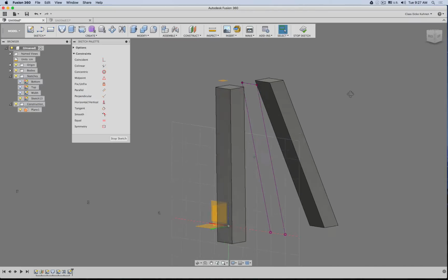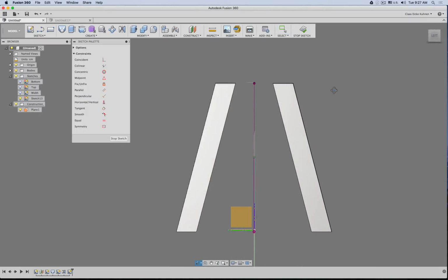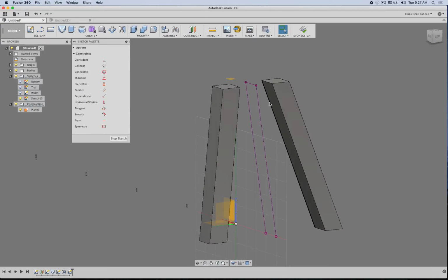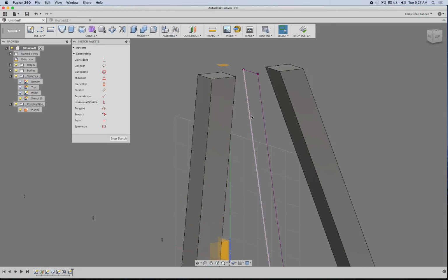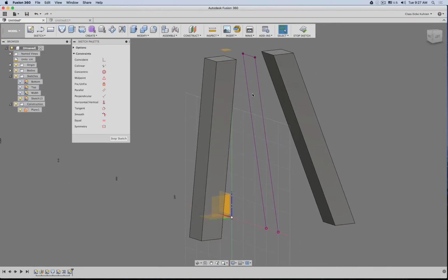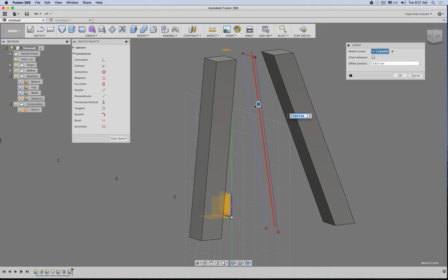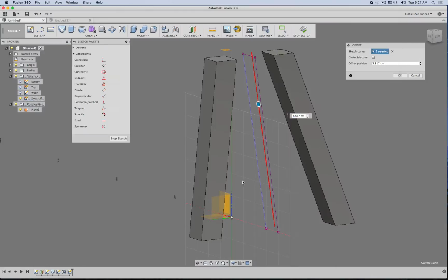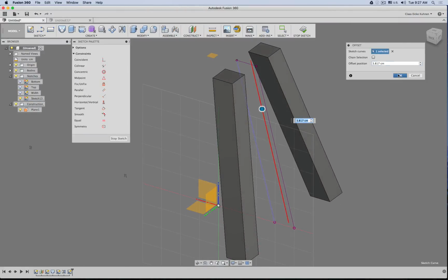Well, this is very simple. The sketch, as you can see now, is vertical. So when we extrude it out, it goes perfectly left and right. And by projecting these corners in, I also have the rotation of these lines. So now I can go ahead and, for example, say offset this line as much as needed. Because if you pay attention, there is a small gap, but it's flush in the corner in the back. Okay, so let's say like this.